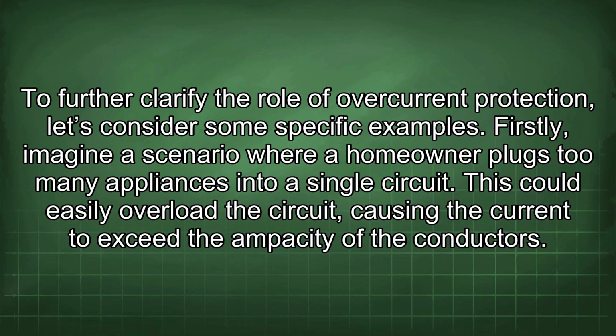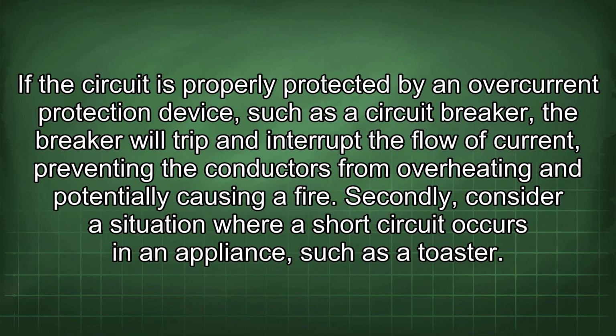Firstly, imagine a scenario where a homeowner plugs too many appliances into a single circuit. This could easily overload the circuit, causing the current to exceed the ampacity of the conductors. If the circuit is properly protected by an overcurrent protection device, such as a circuit breaker, the breaker will trip and interrupt the flow of current, preventing the conductors from overheating and potentially causing a fire.